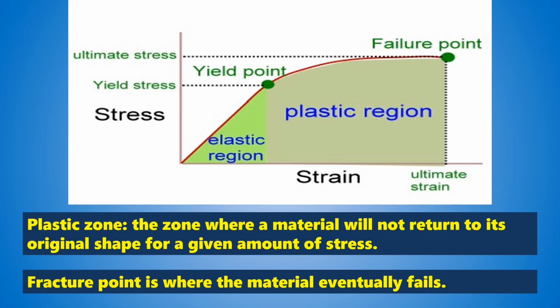That once we removed the force, it didn't regain its original shape, because at the microstructure, the fibrils or the molecules or the grains or the crystals start to experience tears or breakages. That's why we have a permanent deformation in the material.